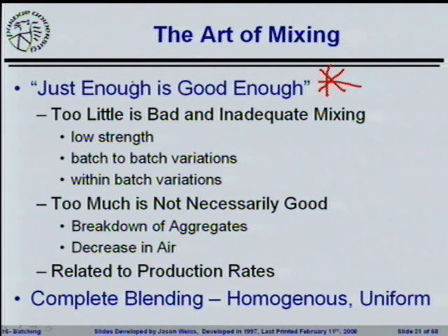Too little mixing is bad because it gives you inadequate mixing, low strength, and a lot of variation. Too much mixing, though, may not necessarily be the best thing in the world. You will start to break down the rocks. They'll actually start to crush inside of the mixer. You can break down things like fibers when they're crushing inside of the mixer. You can decrease the air content.